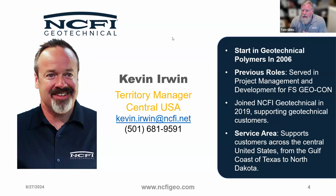Well, it's a tough one because it really depends on what we're trying to accomplish, but the soils themselves are going to make a huge difference. Like if it's needed at 50 feet and you can get to that, then you're having an effect, but only if it's needed. I looked at one building where the soils report said it's crappy down to 100 feet. But our engineers said there's only a zone of influence for this particular structure, because it only weighs so much. It's only going to influence the soils down to about 60 feet. So that's all we really need to treat.